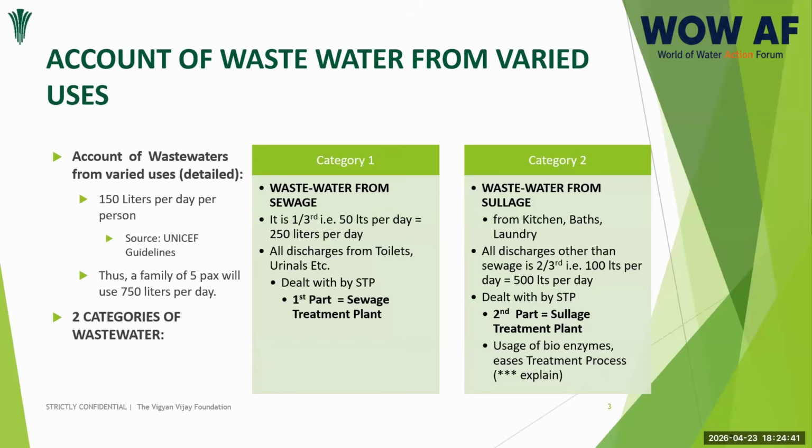You can have first stage sacrificial plants to take care of remediation of water, a second phase to do slightly more remediation of the grey water, and a last phase can give you very good remediation. So the BOD, the TDS, and many other contaminants in the wastewater can all be brought to the compliant level.